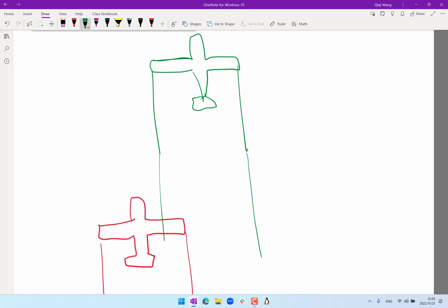Right, so if you want to calculate how much induced flow is there on the red airplane, I would probably split it up into several sections. There is one section over here, one section over here, and maybe split the left wing also into two sections and compute the induced flow on the center of each.